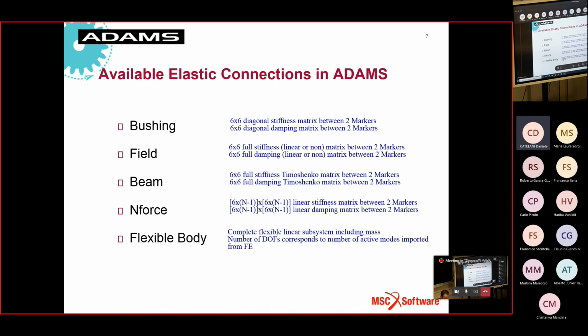When we say modal description, it means that the flexibility is defined not through a full structural analysis, but through a modal analysis, and every mode of vibration is a degree of freedom of the model, and the combination of these modes provides a very accurate definition of the flexibility.